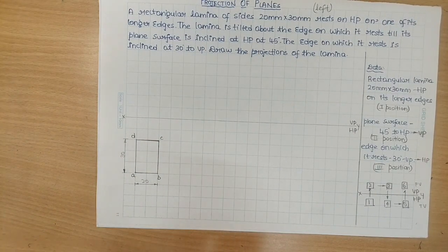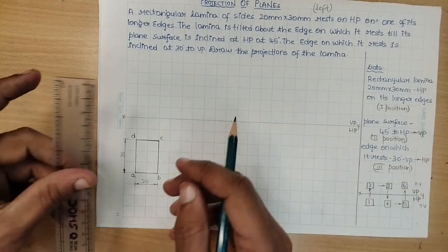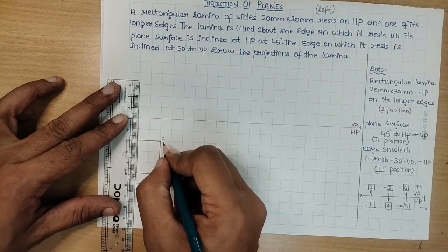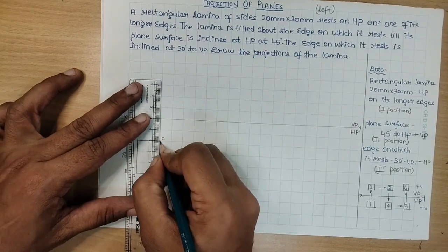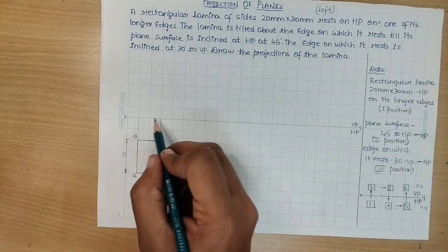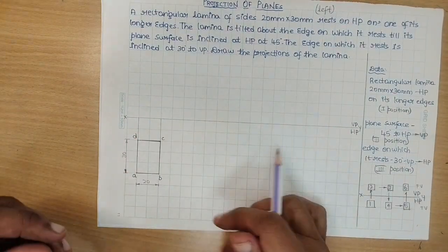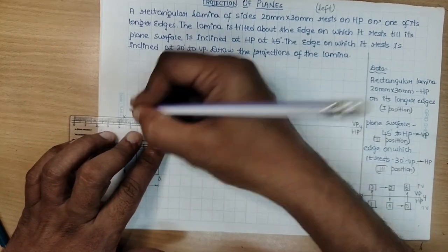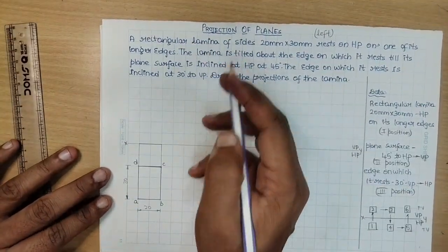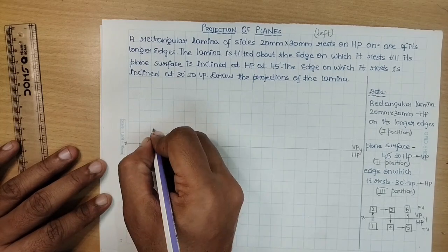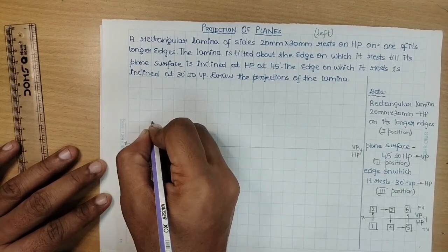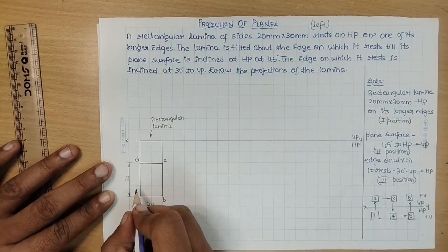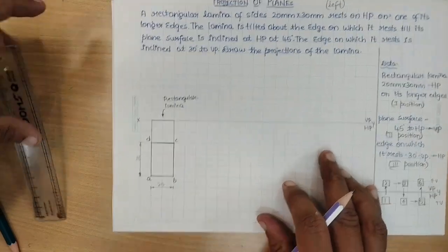Now, make use of scale and pencil. Let us move towards the drawing number 2. Draw a projection line from the points A and D till it touches the XY line. Similarly, projection lines from points B and C till they touch the XY line. Now, let us join the two new points we have got on the XY line, and that would be our rectangular lamina or rectangular surface. They have used the word lamina. Since the base geometry is a rectangle, this is called a rectangular lamina, and this is resting on the longer side. I will update everything.